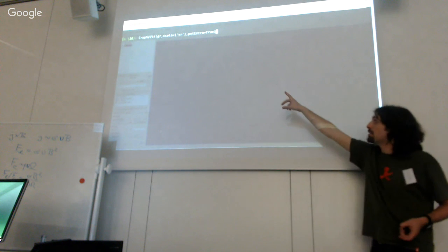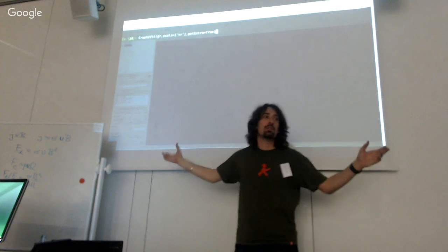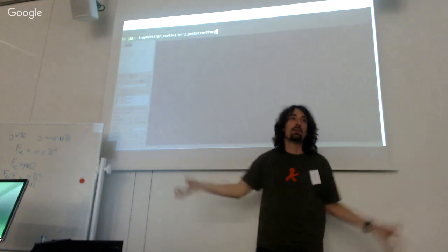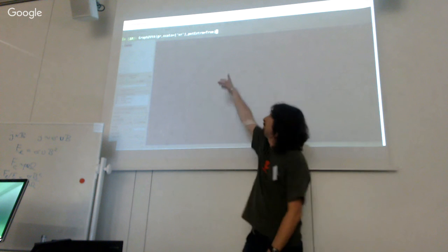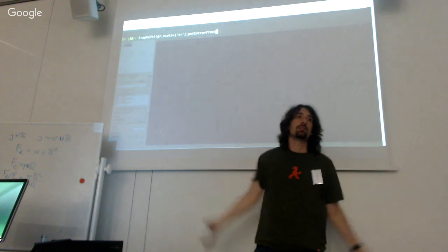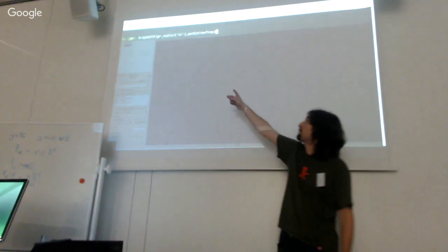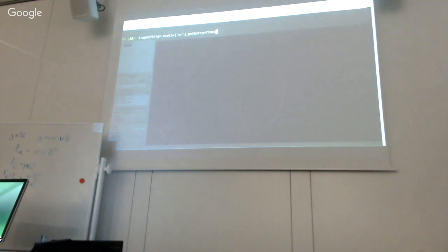And the second option is actually pretty cool. What it's doing here is just doing a potential extrapolation of the field lines outside the spherical shell. So if you want to have your nice dipole and see the field lines closing outside, then you can use this option here, and then you're going to see your field lines closing outside of the domain. So it's just quite extra for potential extrapolation. So it will produce a new file, and you can use this file again as part of your manipulated data.